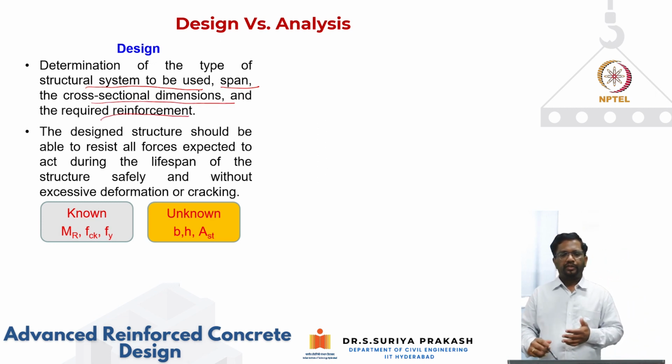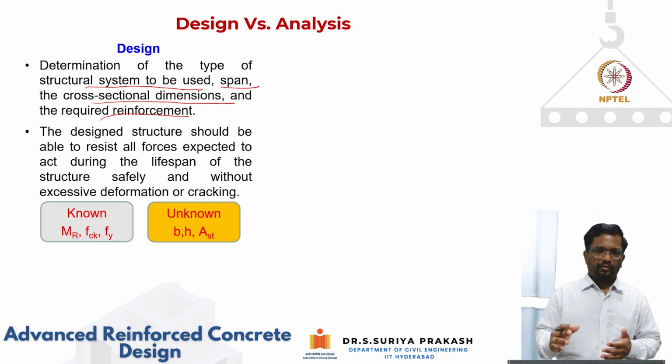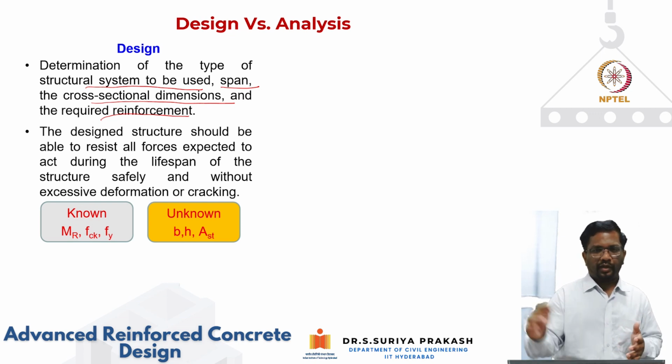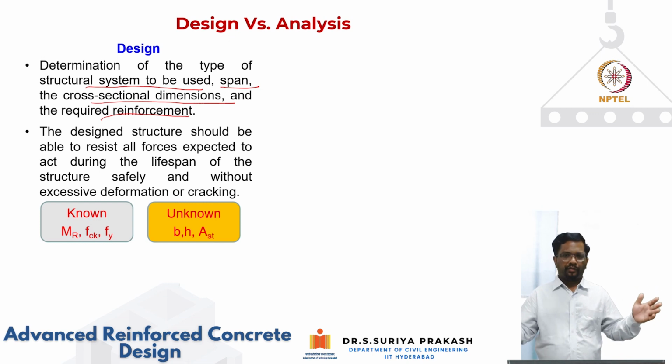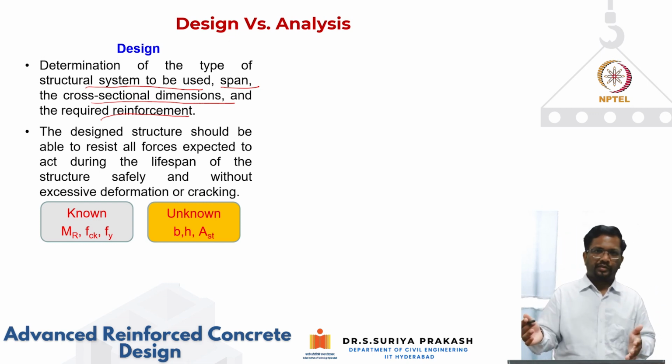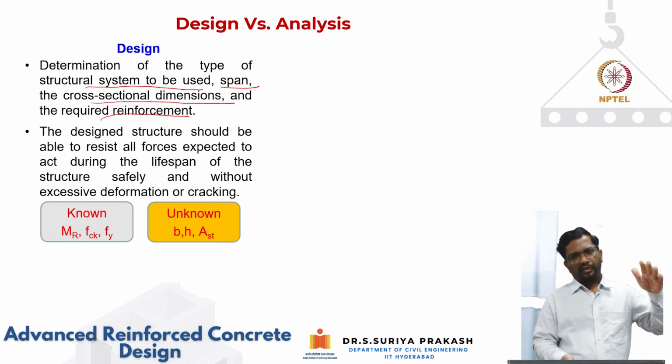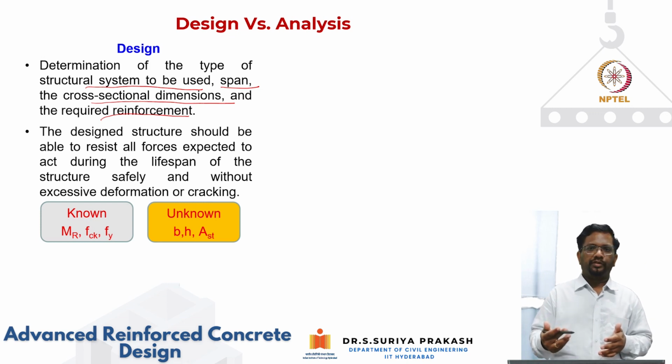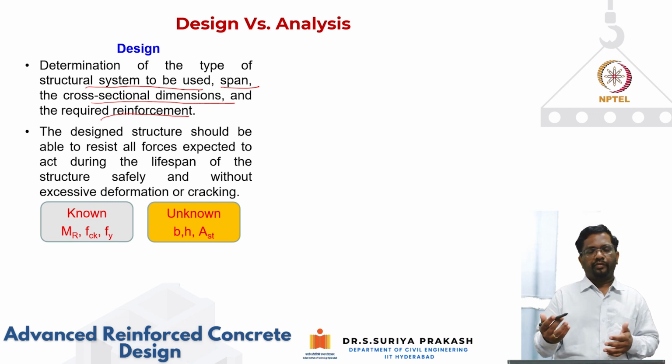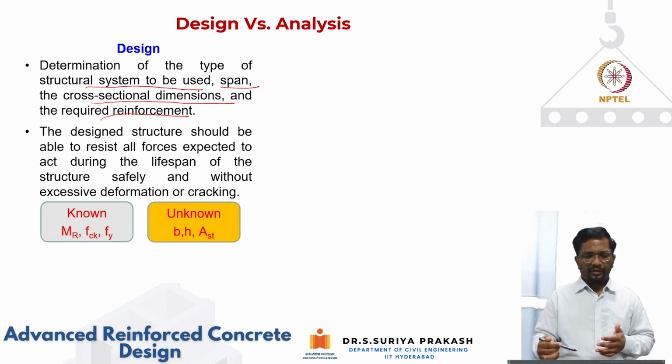This is what design we do. But again, span can be fixed based on your functional requirements from architectural considerations. At the same time, the depth of the member can be fixed based on simple L by D, span to effective depth ratio provisions that are usually given in the code. Those are derived based on past experience.